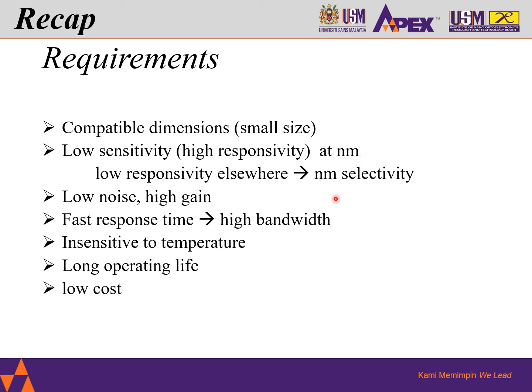Photodetectors should also have low noise and high gain, a fast response time, which translates to high bandwidth, insensitivity to temperature, a long operating life, and of course low cost.